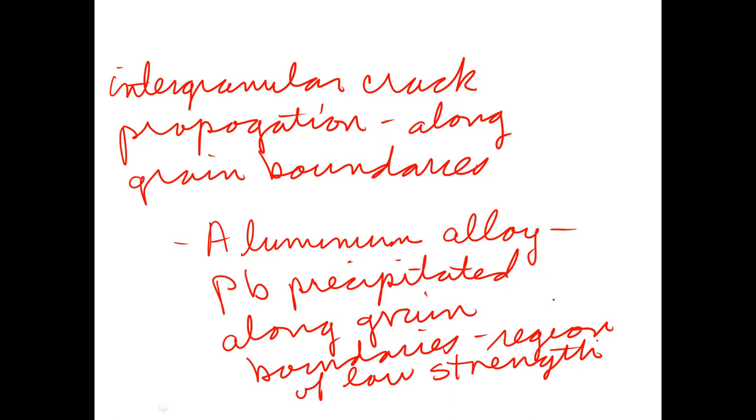In this case, it's purported that there was a Boy Scout troop collecting aluminum cans as a fundraiser, and they had loaded some lead shot in with their aluminum cans to increase the weight and value of the aluminum cans. Then that went to an aluminum smelter. They were remelted. The lead preferentially precipitated at the grain boundaries, resulting in these intergranular failures.